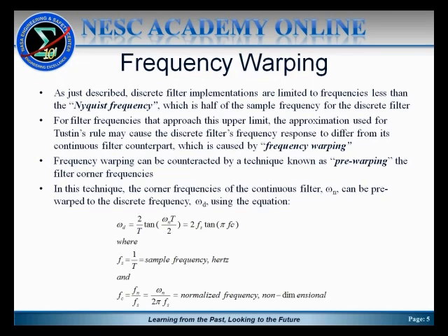You might remember the transformation from the Laplace domain to the Z domain used an approximation for log of Z. That approximation is what we're running into when you have filters, or components in their filter, up close to the Nyquist frequency.